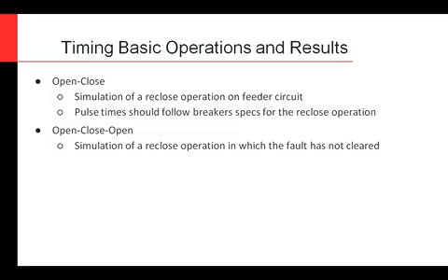And then lastly, there's an open-close-open, which some people test, not as many do, but this simulates now that the breaker, there's a fault on the line, it opens up to clear it, there's a short delay again, it'll close back in, and then if that fault's still there, it'll open again and trip out and stay in the open position until you can investigate or make sure the fault's cleared down the line.